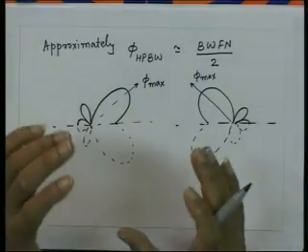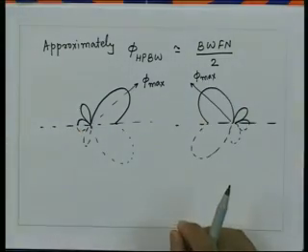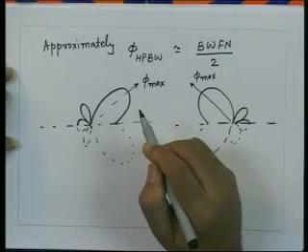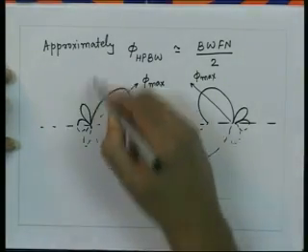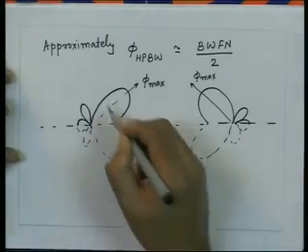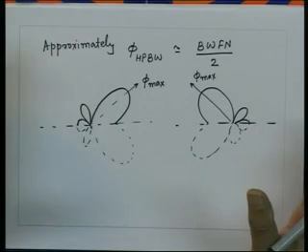So for approximate calculation of the half power beam width of the array, we can do this kind of simplification. We find the direction of the maximum radiation, find the direction of any of the nulls which is visible, and find the difference between these two directions; that is approximately equal to the half power beam width of the array.